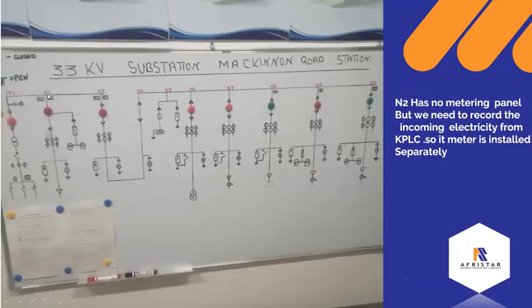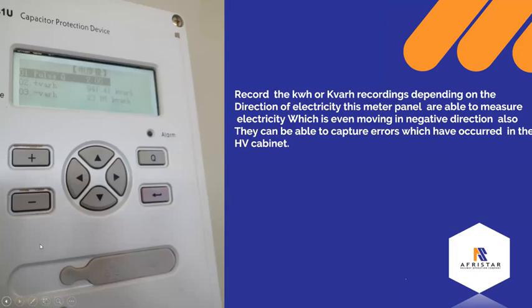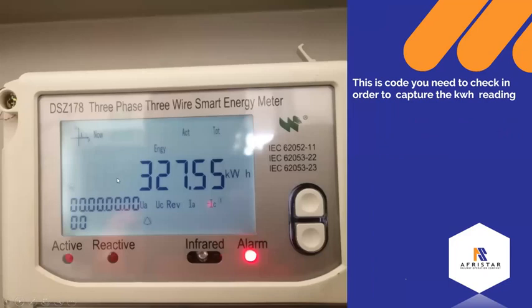So for N2, the N2 cabinet does not have this metering panel, and its metering panel is connected at the control room, and we usually also collect data there. The first one is the active power, and we press these buttons until we have this code, 000.